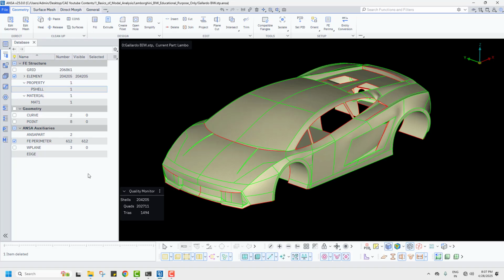After the 6th mode you will get the global modes, and after the 10th mode you'll get all the local modes. Then you'll understand how the components or the subsystems are stiff. If the components are vibrating too much at a particular frequency, then you can understand that the component is less stiff, and we need to add more strength and make it stiffer. That's how we judge it. This is the fundamental idea here.